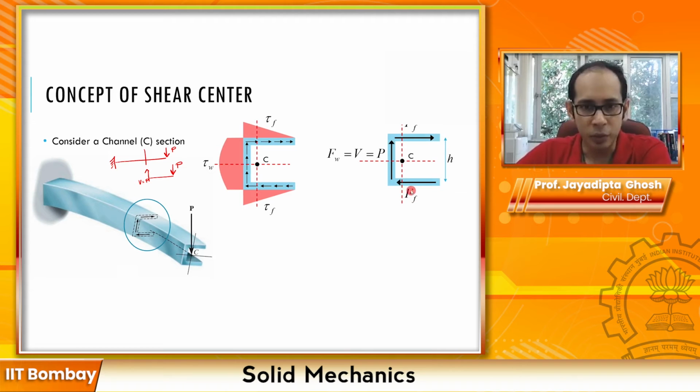Now a quick question: how do I get this Ff over here? It is simple. You can get this Ff because the stress varies from 0 over here to maybe a highest magnitude, something over here. So it is going to be half times the length of this one times the height of this one. That will give you the dimension of the length, and if you multiply by the value of the peak stress over here, you will get this Ff. We'll do a problem example there. You can see how we get the forces from the shear stress distribution.